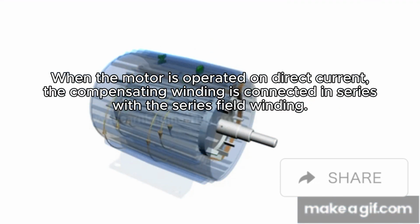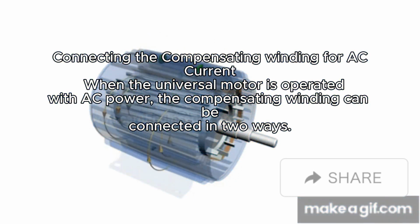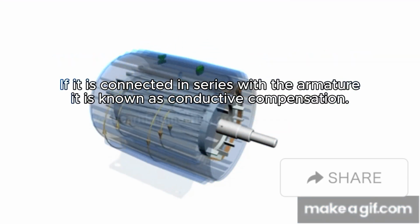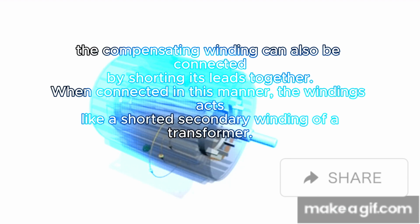When the motor is operated on direct current, the compensating winding is connected in series with the series field winding, connecting the compensating winding for DC. When the universal motor is operated with AC power, the compensating winding can be connected in two ways. If it is connected in series with the armature, it is known as conductive compensation. The compensating winding can also be connected by shorting its leads together.